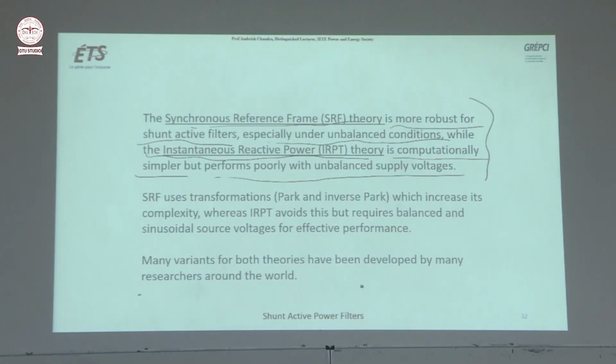This is what people say. SRF uses transformation and inverse transformation, which increases its complexity, whereas instantaneous reactive power theory avoids this, but requires balanced and sinusoidal source voltage for effective performance. But now many variants are coming. Researchers try to modify SRF and instantaneous reactive power theory, and they say it's working fine. In most cases it really works fine, nothing to worry about.